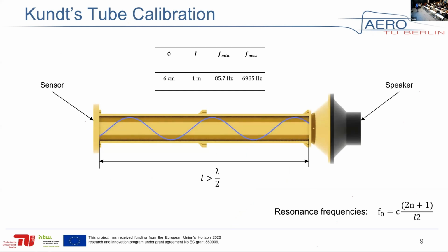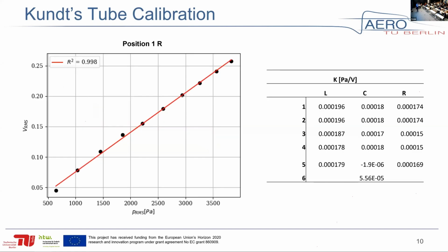and we get constant pressure fluctuations. And by doing that, we achieve this calibration matrix for our sensors, and this is just one position. And you can tell the response is quite linear. Here some sensors are broken, and these two are missing because the acquisition system we have used is only 16 channels. So we've removed a couple of sensors.